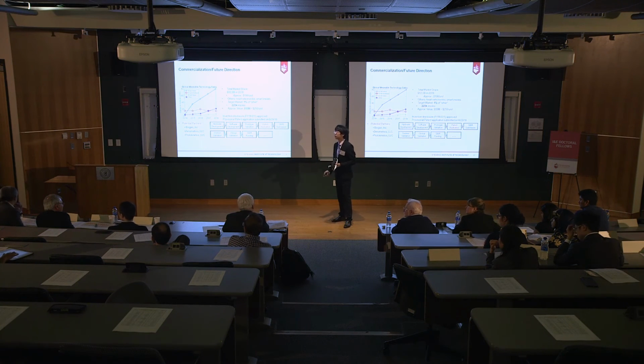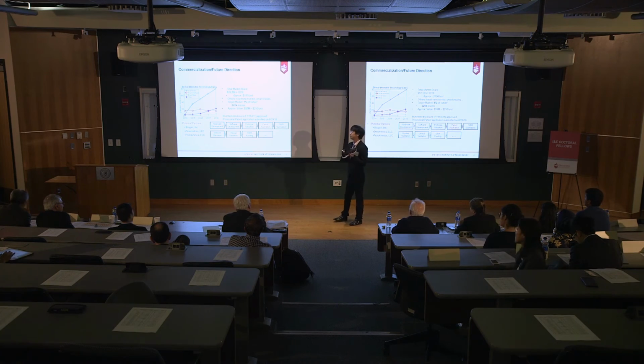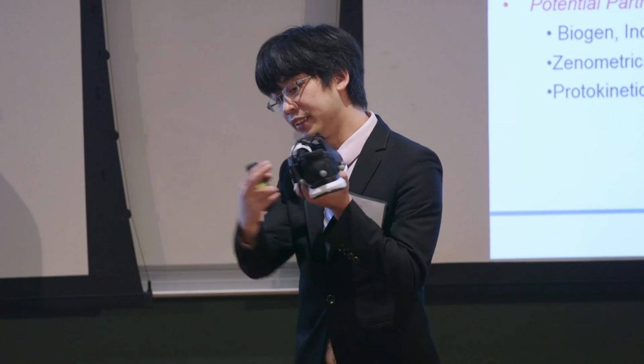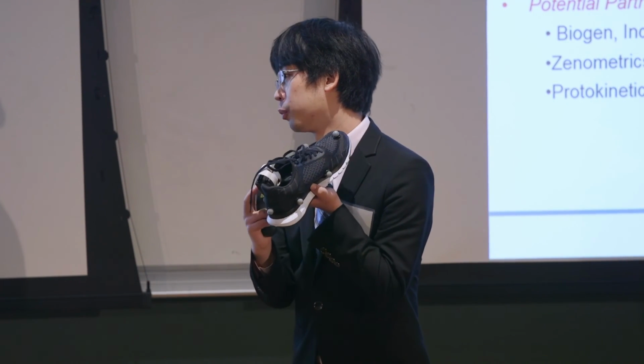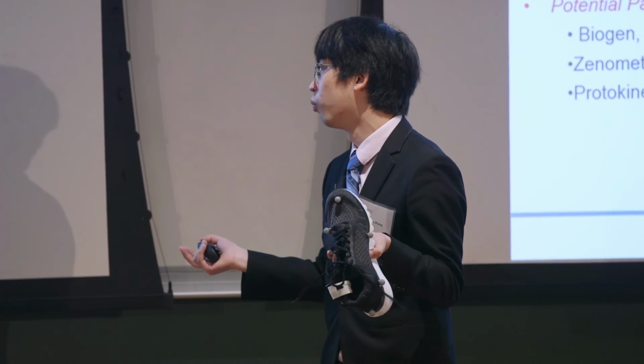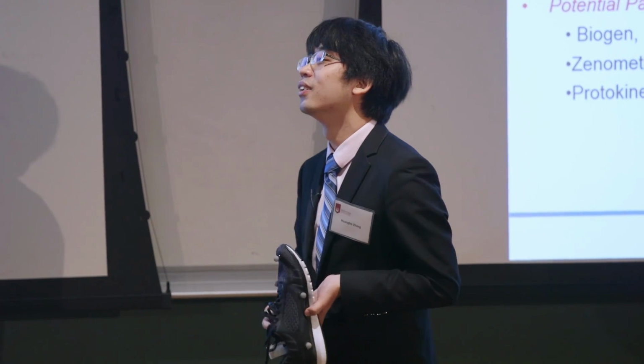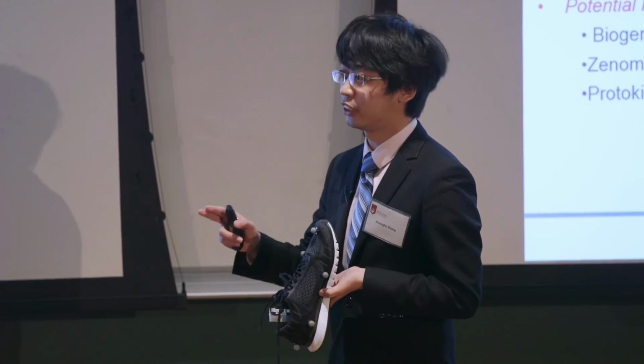What are your power requirements on that? Because when I hear that you use Wi-Fi and all of that, along with the sensors that you're using, you may actually need more power than the others. So how long will the battery last? For now, the battery inside this whole logic box lasts 1 hour. But if we use a much more powerful, expensive battery, it will make it heavier. Yeah, it's a trade-off here.